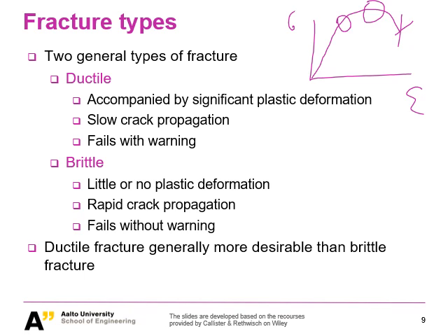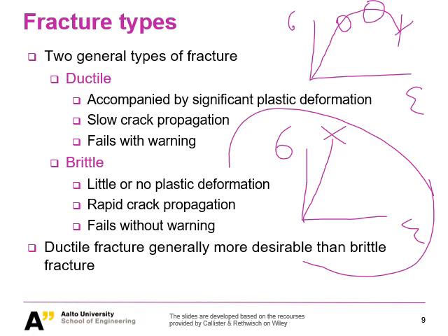Let's move on to brittle fracture. As we have drawn before, still in the stress-strain diagram, for brittle fracture we have such a type. So it is obvious that there is little or no plastic deformation, of course. What I need to tell you is this is a statement based on macroscopic observation, so observation based on this kind of stress-strain curve from a tensile test.